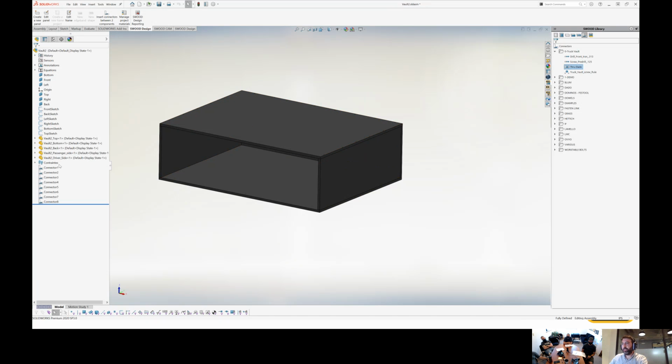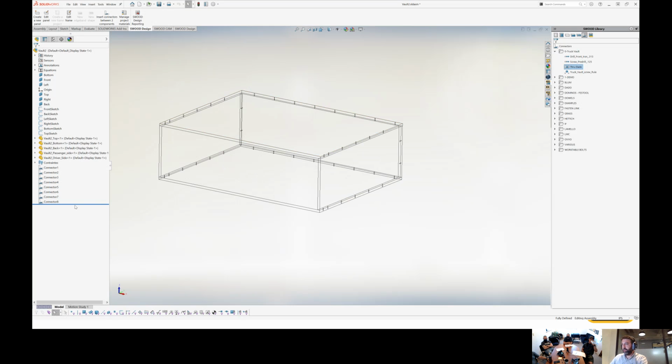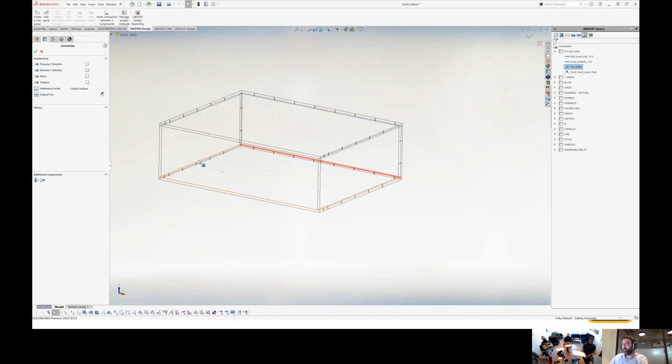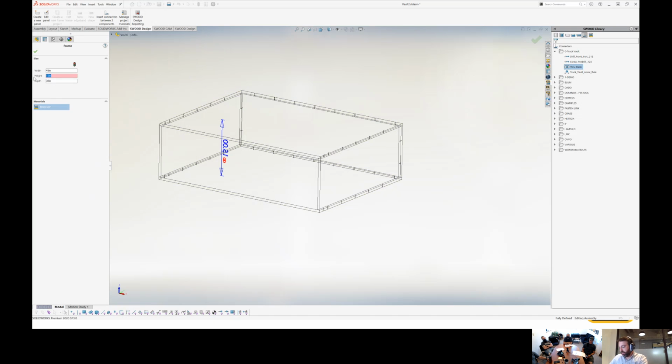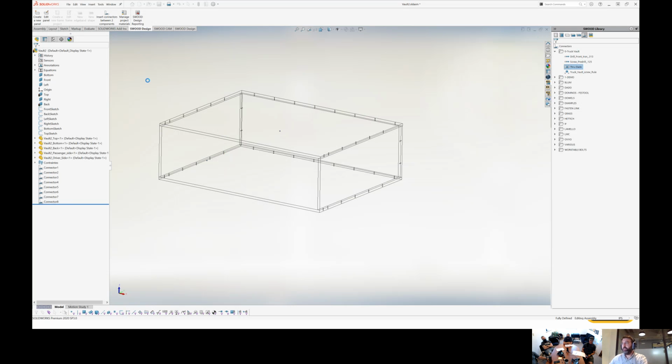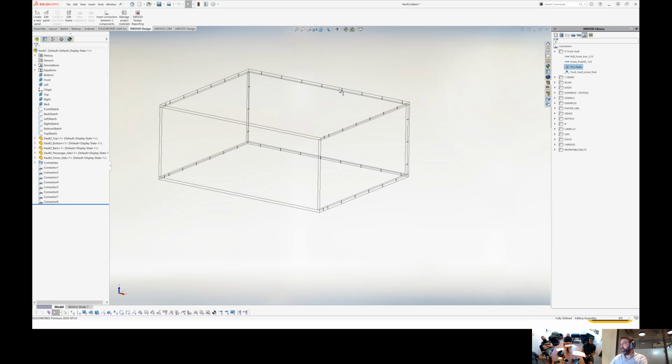So what we can see here now is we got additional feature inside our SolidWorks Preview, and we have just like that the drilling done, and at any time we have the possibility to edit any rule to be able to change, for example, the side offset here and update everything just like that. And obviously when we come back and change the dimensions, for example, here, all the positioning, all the drilling will be updated just like that.